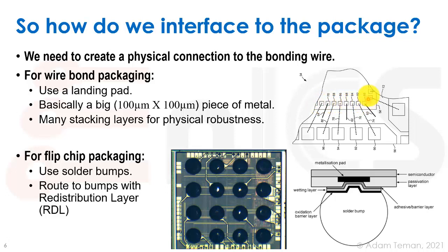So these are the pads on a wire bond chip, and here the machine will connect them from one of these pads out to the package itself, which has much larger pads, which we can really deal with normal machinery or even manually. Okay, but they're pretty big, so they're about 100 by 100 micron. They can be smaller, but that's the kind of order of magnitude of the pitch. The smaller they get, the more expensive it'll be, and the more problems you have, constraints on what different angles you can do with the wire bonding and stuff. And these are different types of DRCs that you will get actually from the package house, and you'll have to check. Okay, so that's what a pad is.